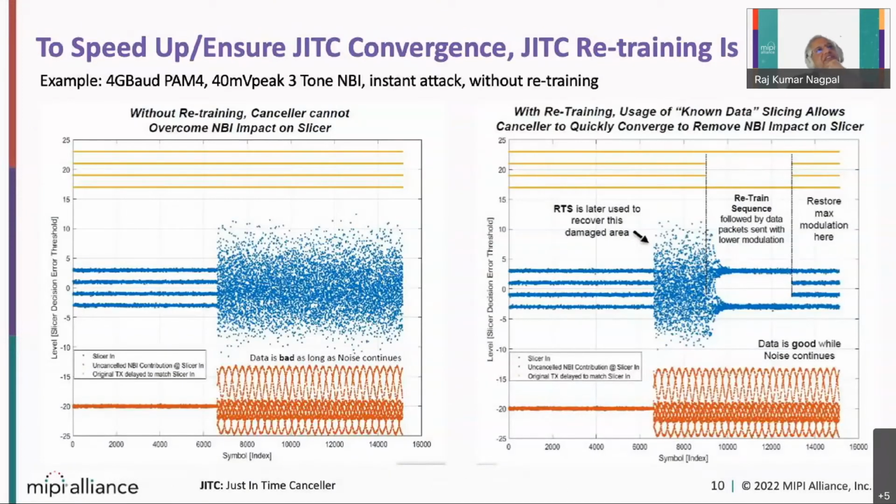So this particular slide is giving an overview of an aggressor event happening, and how my receiver is going to really correct the situation. Here you see, without retraining, without canceller, you got a very high EMC noise, and your link is lost. Immediately on the detection of packet failure, the retransmission event is really initiated. Okay, now it depends upon the packet lost.